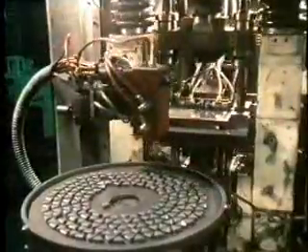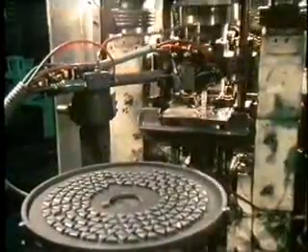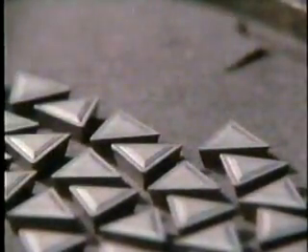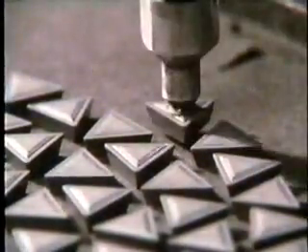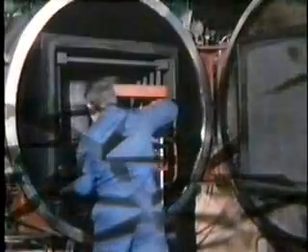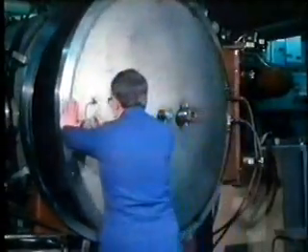Cemented carbides normally contain 70 to 90% hard particles, together with 10 to 30% cobalt binding film. The more cobalt present, the tougher the cemented carbide. Unfortunately, increased toughness results in decreased hardness and resistance to abrasion. So the next stage is sintering in an oven at a temperature in the region of 1600 degrees centigrade. A cover gas of hydrogen prevents the oxygen in the air from damaging the insert. The result is a fully hardened insert.